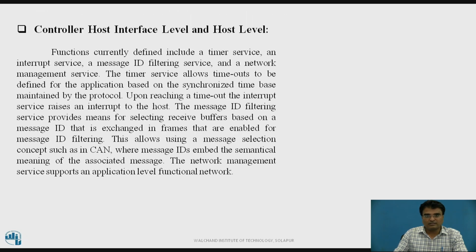Controller host interface level and host level. Functions currently defined include a timer service, an interrupt service, a message ID filtering service, and a network management service. The timer service allows timeouts to be defined for the applications based on the synchronized time base maintained by the protocol. Upon reaching a timeout, the interrupt service raises an interrupt to the host.